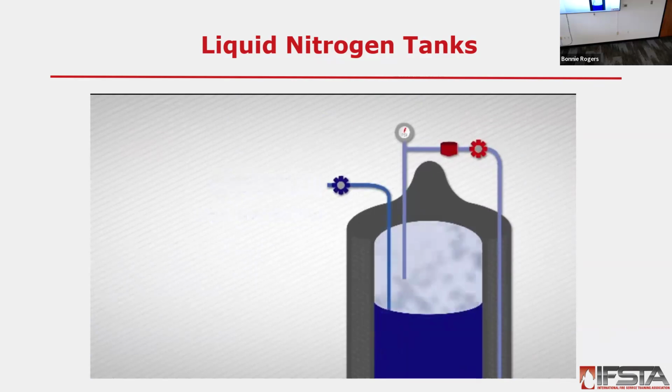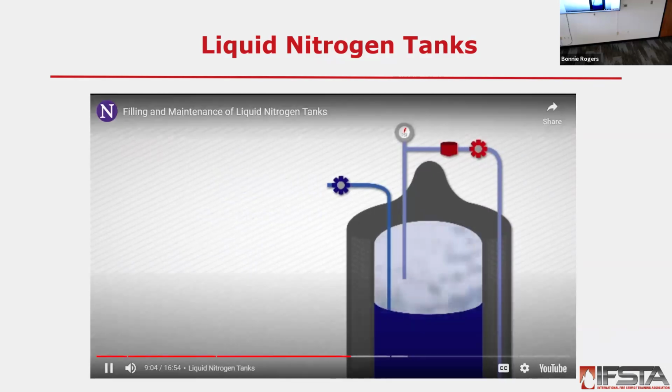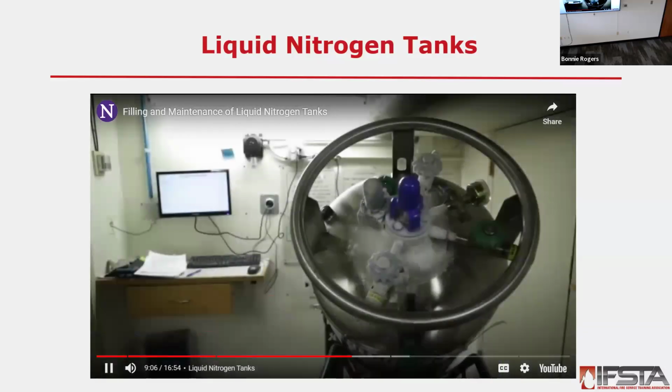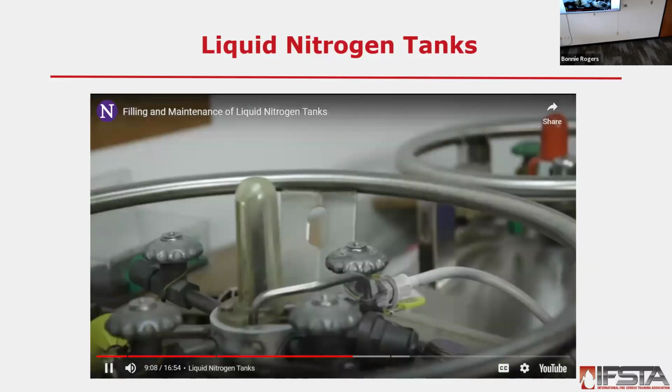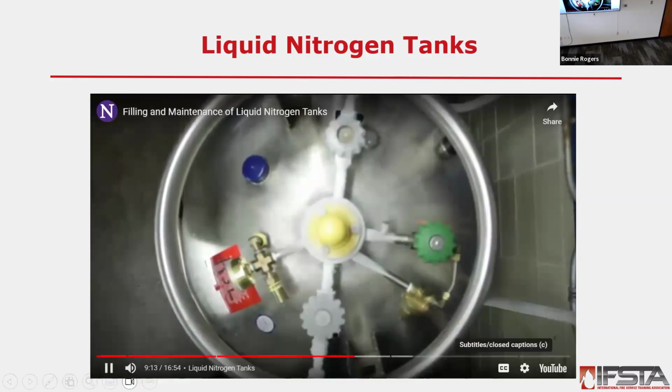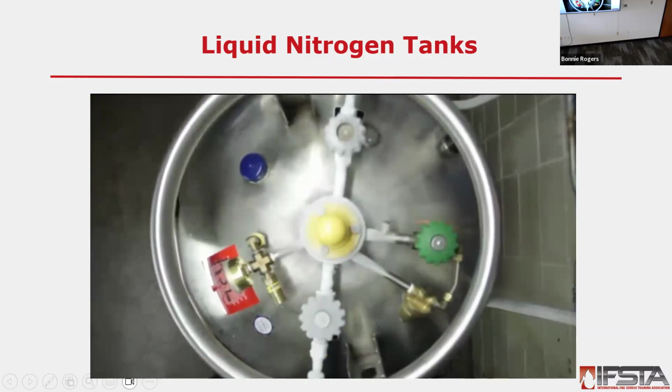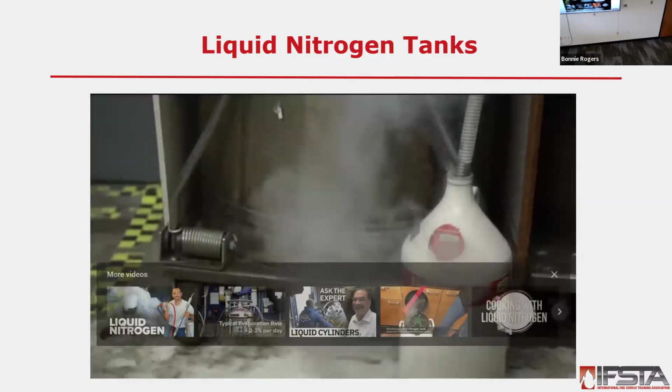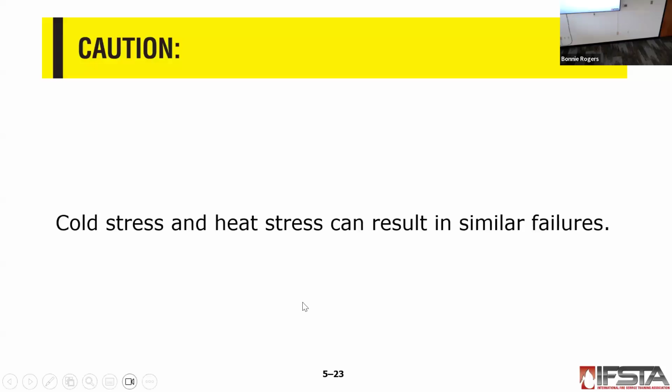Keep in mind that opening the pressure builder circuit will not immediately increase the pressure inside the tank. The pressure building process may take several minutes. Become familiar with the different cylinder pressure builders you may work with. Once a pressure builder regulator is set, it should not be changed. Transfer of liquid at high pressures can...